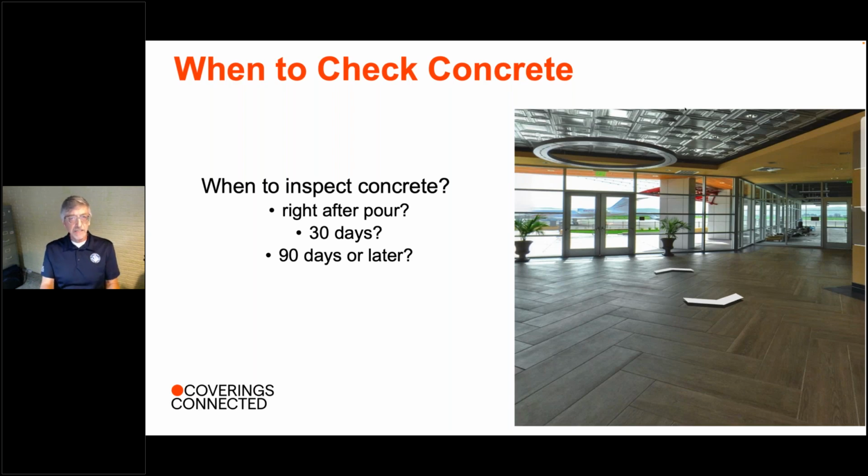And when the concrete is poured, it's allowed to cure for a number of hours or a couple of days before the concrete contractor comes back in and checks it for flatness using their scale called an FF scale. They can test in certain areas of the concrete, usually in the middle of the pour, and they find whether it meets their requirements for flatness. If it does, then they're down the road to the next job.